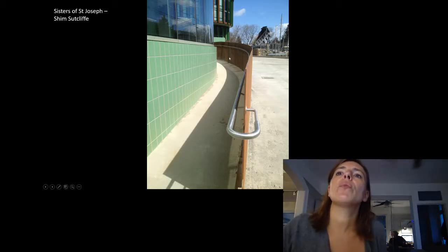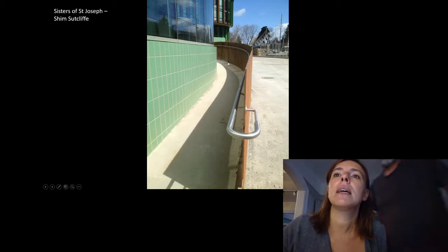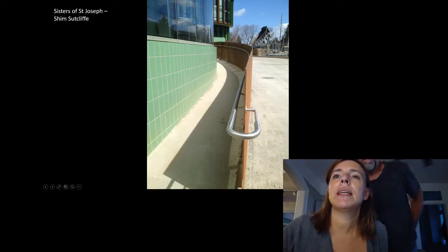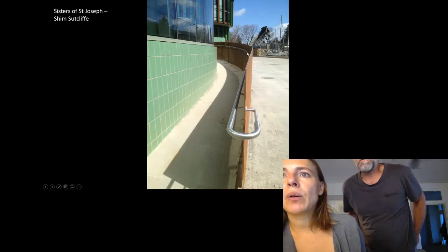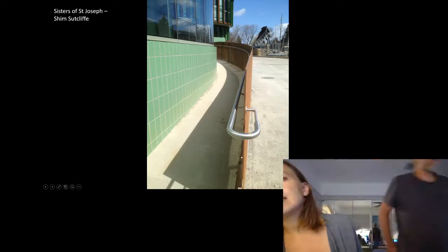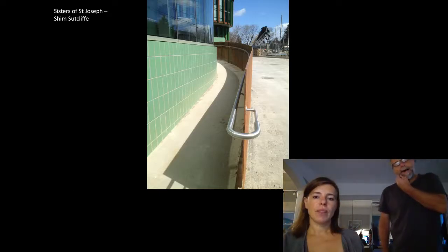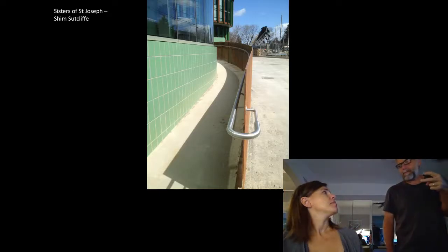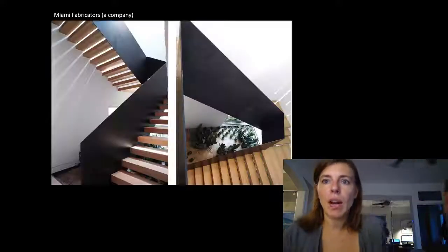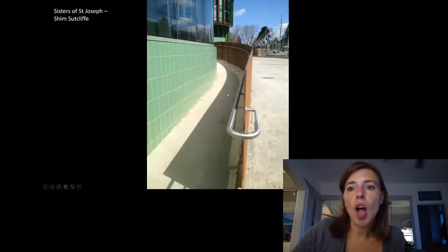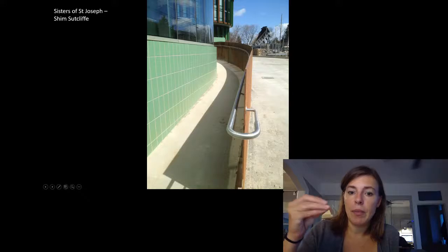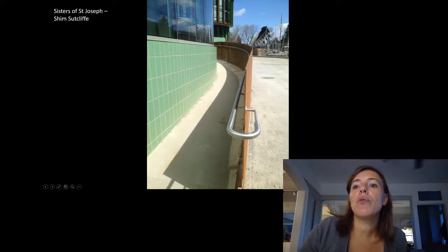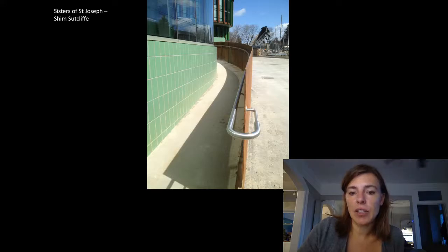Do you remember, Dave? Were these pickets or posts locally connected, or was it continuously connected to the concrete? The plate was continuously connected. I don't think there actually are posts. I think that's right. That's just the welding or shadow lines. Okay. So how was it continuously connected to the concrete? I think it had Nelson studs. It was actually cast in. Okay, so very similar to what I had just said about this. In the shop, so that they wouldn't see the kind of damage, they welded on elements, and then they held it in place, and it was also the formwork for the concrete along the edge.